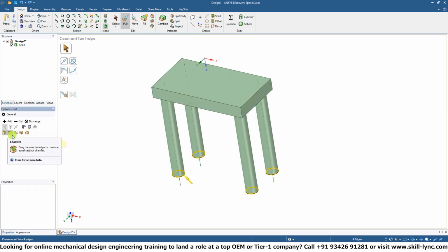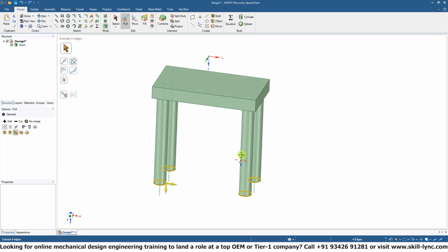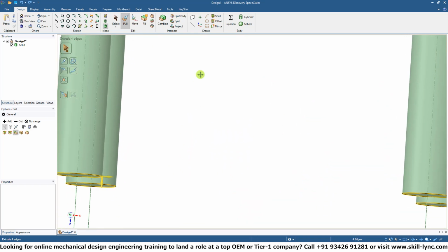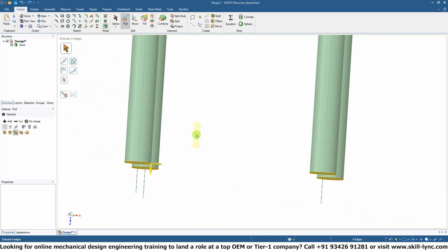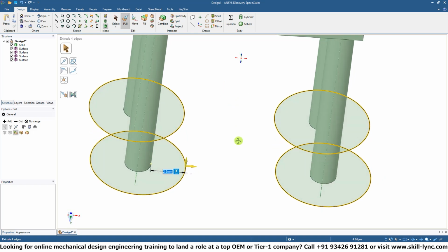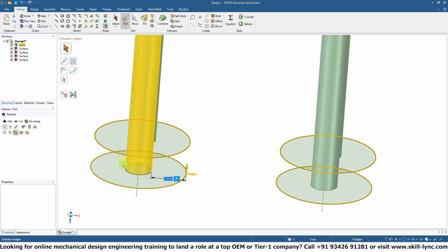And then if we chose chamfer, we'd be using the chamfer. So let's select the extrude edge tool. What this does is it gives us two yellow arrows over here, one vertically down and one horizontally. If we click and drag the horizontal arrow, you can see how it extrudes horizontally the edge that we chose along the perimeter of the feet.